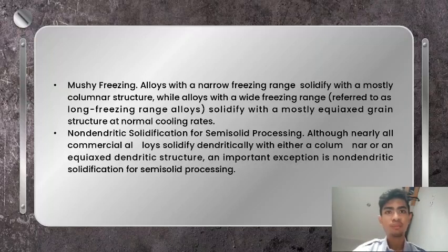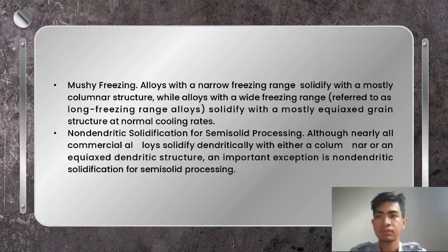Semi-solid alloys are produced with a unique non-dendritic microstructure. With important advantages for bulk shaping, semi-solid alloys flow easily and can be injected into a mold cavity, much like the injection molding of plastic. This behavior arises from the globular microstructure of the semi-solid mass.